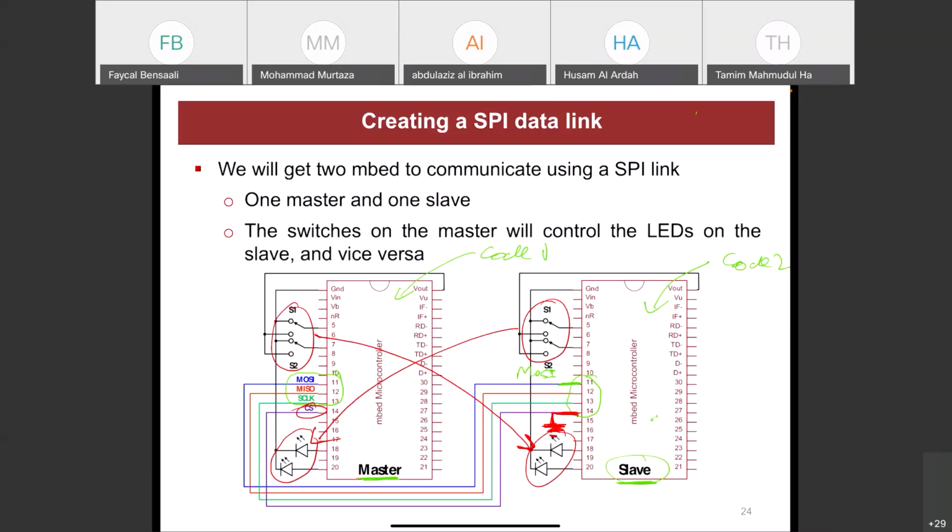Because if you put everything in one microcontroller, for example, in real-time applications, you will not have a real-time response, because you have a very large code and it will be very slow. So we do parallel processing. We have multiple cores working together in one application. Again, this is the simple code just to show you how to send data. So sending data is the same way. You will send it the same way, by using SPI, of course. I'm talking about SPI here.